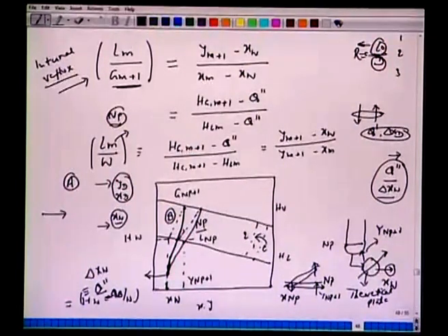So, we have the operating line and we have this tie line. That is what we are doing here, tie line, connect this to the difference point x_W, then connect to this Np, we get this L_Np here. So, again we can continue with this G_Np plus 1, we have G_Np, G_Np minus 1 from this side, as well as we have done it from the other side here.